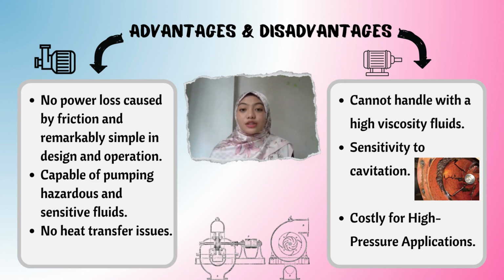Next, the disadvantages of the centrifugal pump. The first is that it cannot handle high viscosity fluids. The second one is that it is sensitive to cavitation. And the third one is that it is costly for high pressure applications. To achieve high pressure, we need to add equipment such as a booster pump or multi-stage pump, which increases the capital and operational expenses.